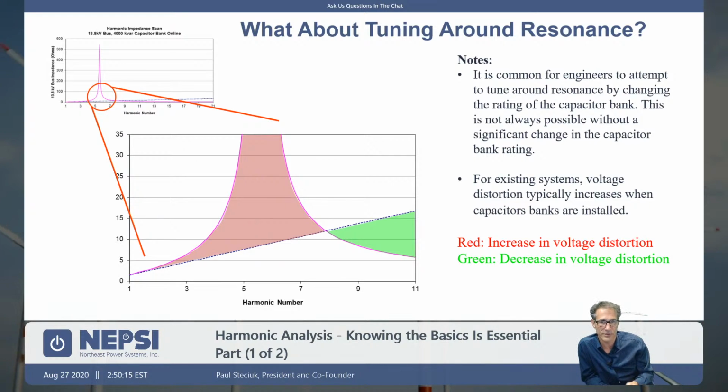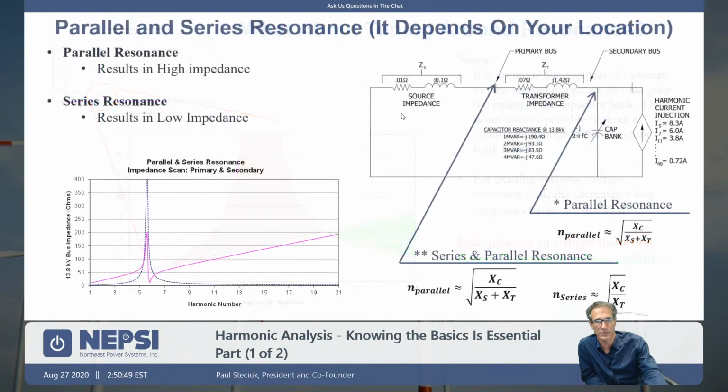And it just so happens, and it's normally bad luck, that when you do power factor correction with standard power capacitors, more often than not, the resonance is going to land in that 5th to 7th range. You're going to get an impedance curve that looks like this. The net result is an increase in voltage distortion in your plant. So our recommendation generally is, if you have drives in the plant, even if they're active front-end drives or high pulse drives, install some type of filter into the network or a detuned cap bank. And that's going to be the topic for next week, how these devices help you out.